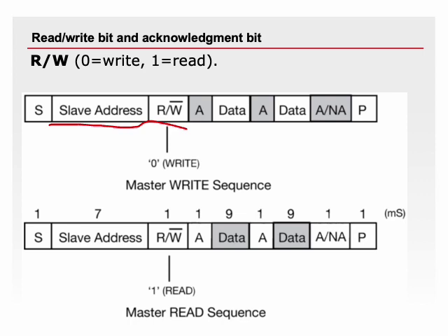This byte is then followed by one acknowledgement, ACK, bit from the receiver. The ACK bit allows the receiver, or a slave with the correct address, to communicate to the transmitter that the byte was successfully received and another byte may be sent. It is worth noting that to send an acknowledge bit, the receiver shall pull down the SDA line during the high phase. The SDA line is stable high.